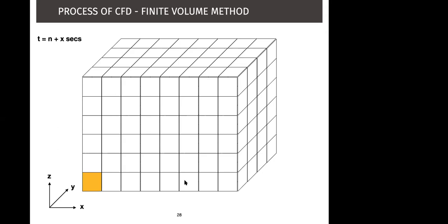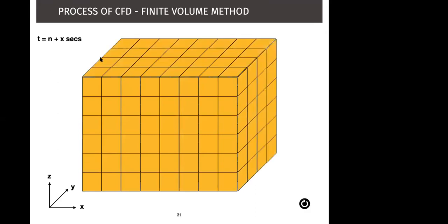And then we would again do the entire iteration. And again, for the next time step, which is t equals 0.15 seconds, once this time step is completed, this would now become the initial conditions for the time step moving forward. And this process is repeated until we receive a steady state condition.